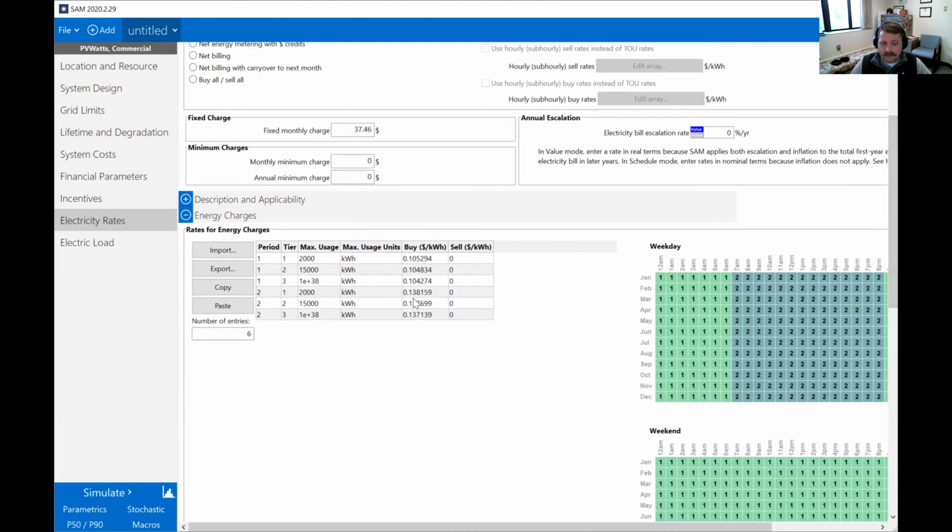These costs of electricity are fairly high, and so they likely include the demand within that rate. If this had a demand rate like $13 per kW, this might be maybe 5 or 6 cents, because again, we're paying for the electricity in two different ways, both energy and demand. In this case, we're only paying for it one way, so it's going to be a little higher rate.